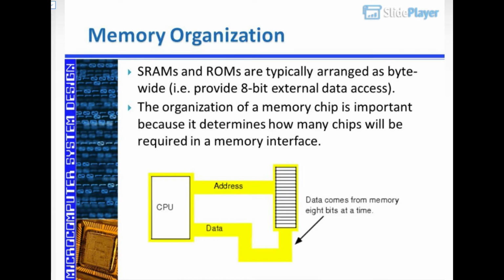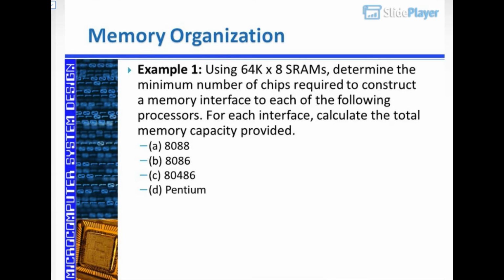Memory organization. SRAMs and ROMs are typically arranged as byte-wide, i.e., they provide 8-bit external data access. The organization of a memory chip is important because it determines how many chips will be required in a memory interface.